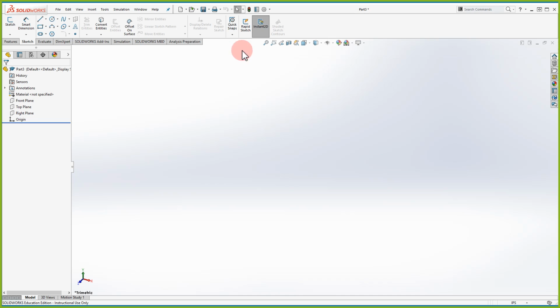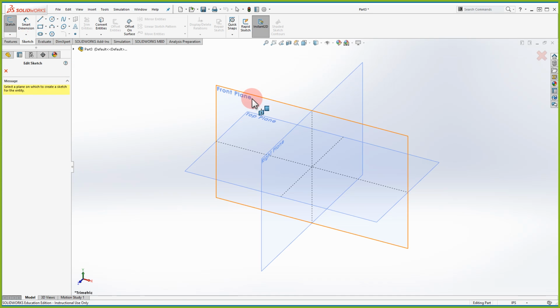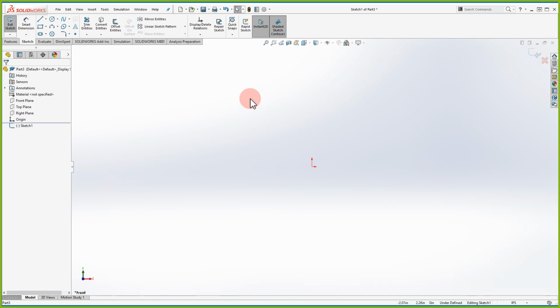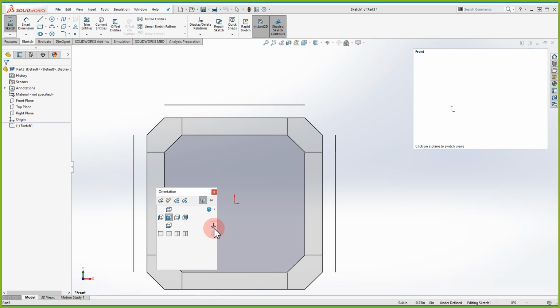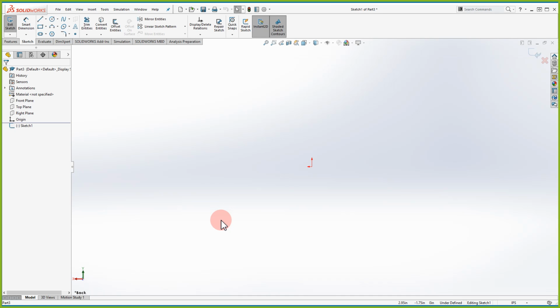So now we're going to talk about this little icon right over here called relations, which is blacked out. Why is it blanked out right now? It's because we don't have a sketch that's currently using anything. So if I just press sketch and I choose my plane like before, front, then I use the space bar like I'd like to do and do middle. It's in the middle again. I didn't have to do that extra piece. Let's go choose this circle again.